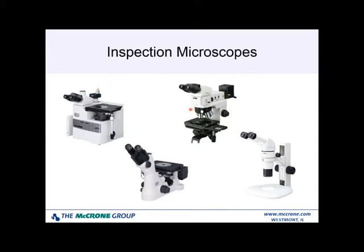This instrument here is considered an upright materials microscope, looking a little bit more familiar with microscopes that you're used to. Eyepieces are up here, stages here onto which you put your specimen, but the objectives are at the top of the instrument and they look down on your part. You can have two different types of illumination, either reflected light illumination or transmitted light illumination through the part. So if you have a translucent part, a clear part, this would be the type of instrument that you'll be looking at.